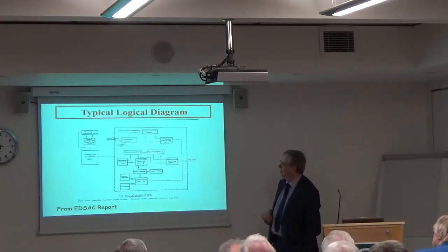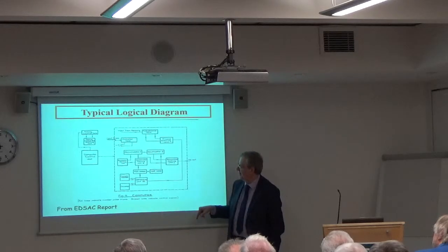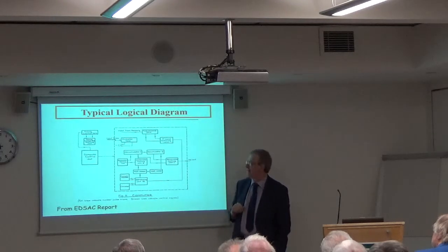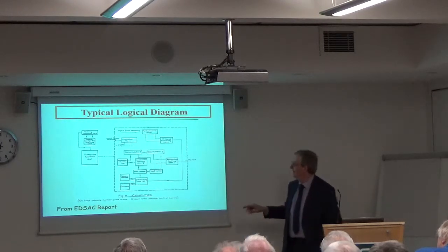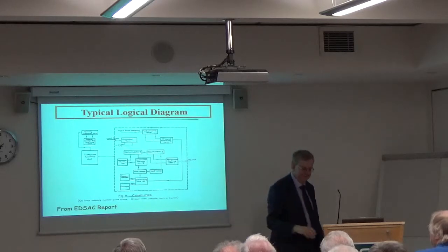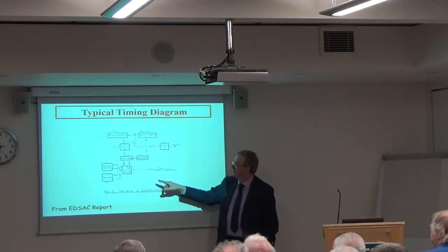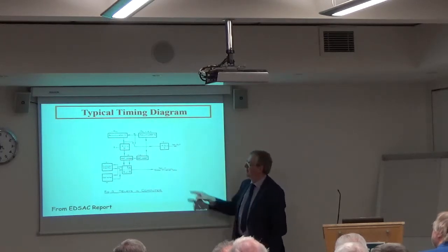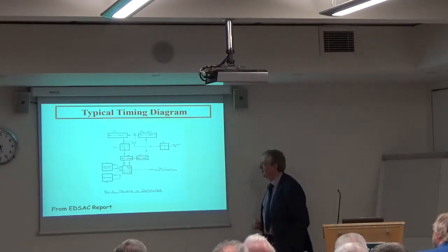This is what we now call the arithmetic unit. It shows the two halves of the accumulator, shifting units, half adders, complementers, collators. So how the machine does arithmetic, and most instructions are concerned with arithmetic in EDSAC, is pretty well defined by that diagram. So you get pictures like that, and these often helped us understand what individual chassis might do, because often these blocks corresponded to a chassis. Alongside those, there were quite often helpful timing diagrams that told you how many pulse intervals apart these various units were, i.e. what delays were in the machine. And that helps you in the design of main control that has to poke these things at regular intervals. It tells you when it's got to waggle the appropriate signal.